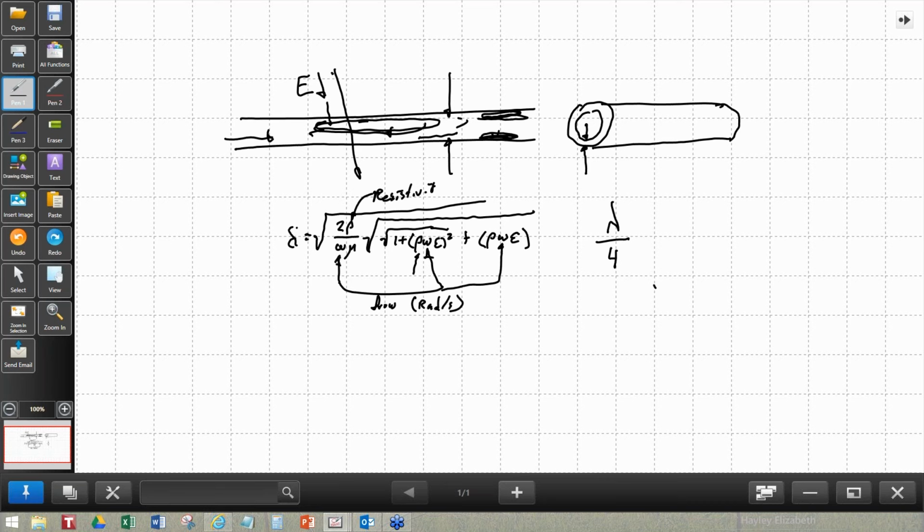So the second thing is you can go into this equation and you can see that we have a term that is recurring. We can look at that term, and you can plug in the resistivity, the frequency, and the dielectric constant, and you can actually see when that becomes significant in comparison to approximately 1.